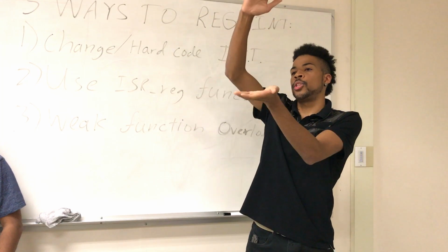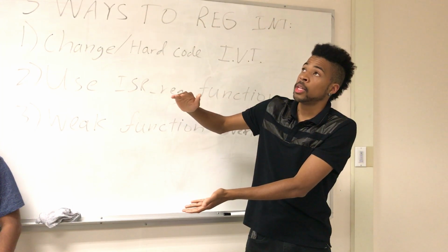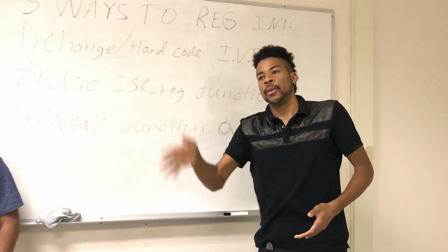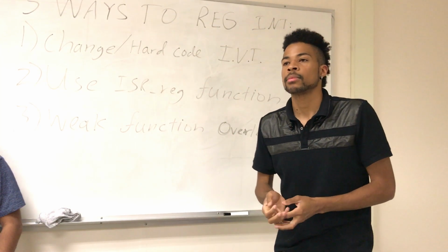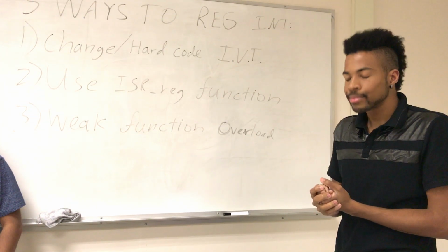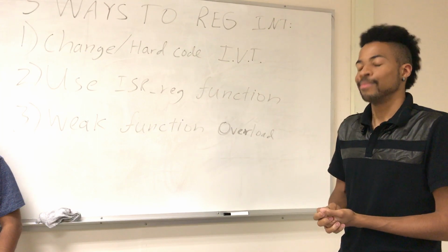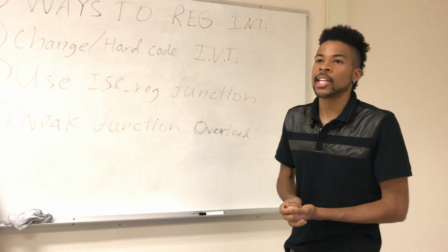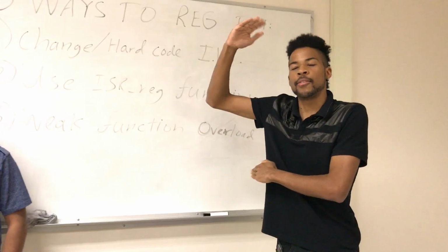So you'd have one service routine somewhere, and then you have your data bank of all the registered IOs and what type of functions they can run. Okay. So you just check the status register for which pin got set, and then whatever pin that was is going to reference the data structure with the function that you want to attach to that pin. Yes. It's like coming up with an interrupt vector table for the entire GPIOs effectively. That's effectively what you're creating.